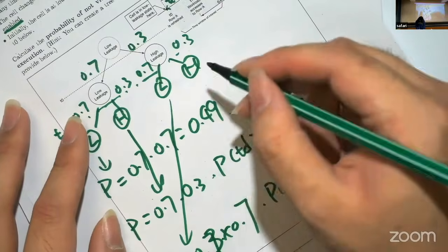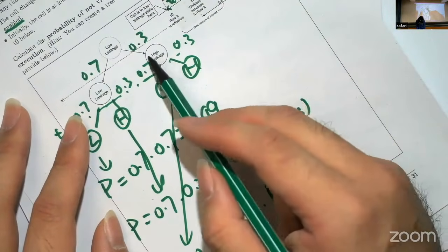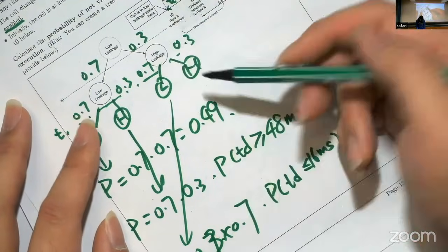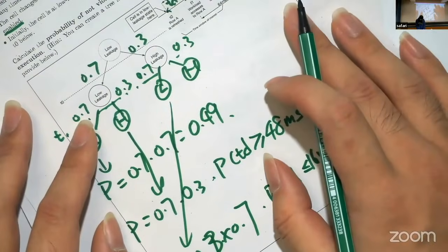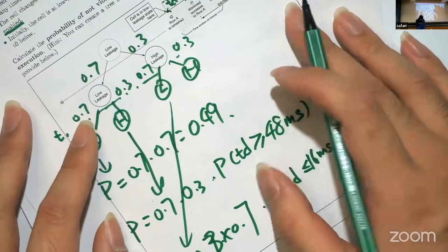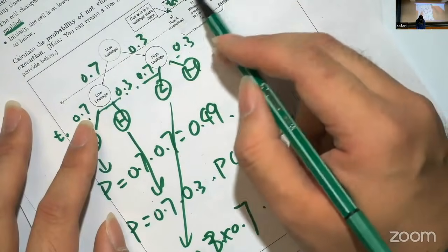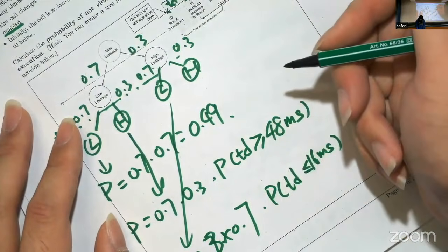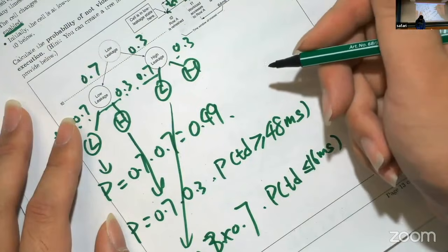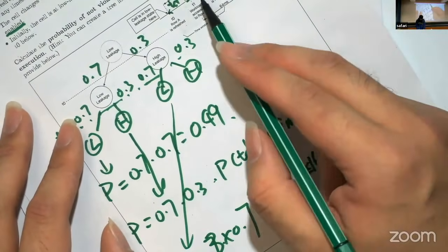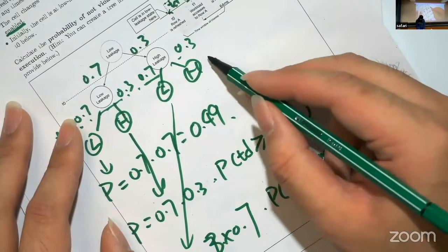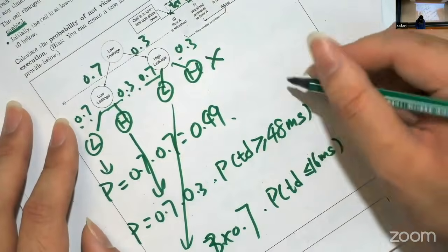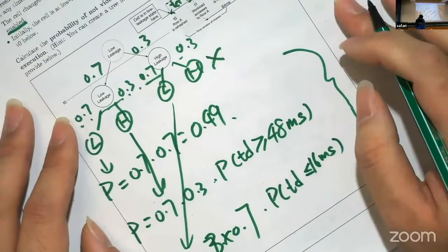Yes, and then for this final H state, both are in the high leakage state. So this cell can only retain data for 16 milliseconds, and there's no chance these two intervals can extend to 64 milliseconds. So in this case, no matter what, there will be a retention failure. So this is impossible. Then the final probability is just the sum of these three.